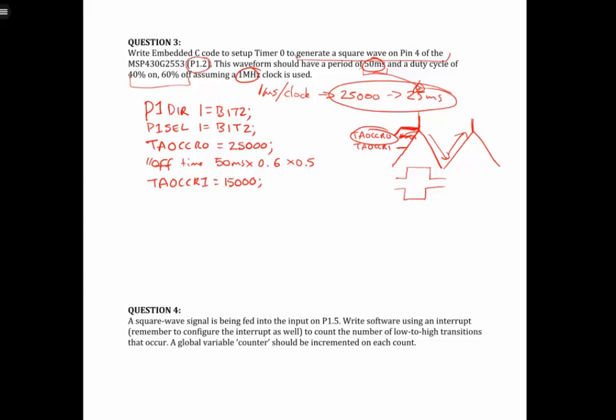Now we need to set the output as toggle select. So TA0CCTL1.